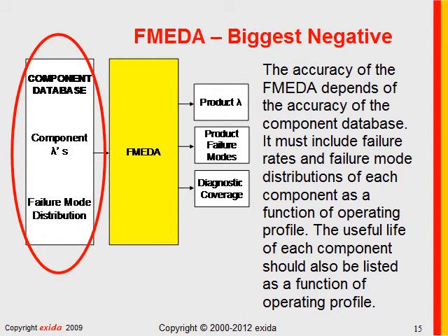Now, for those of you who are thinking ahead, you've already recognized a problem. The biggest negative in the FMEDA is the component database. What if the component database is no good? Well, obviously the results will be questionable.